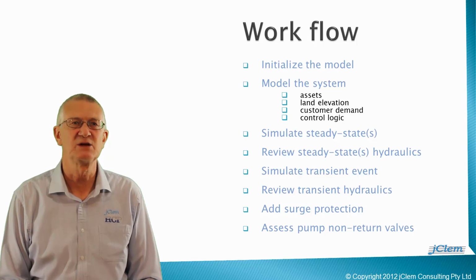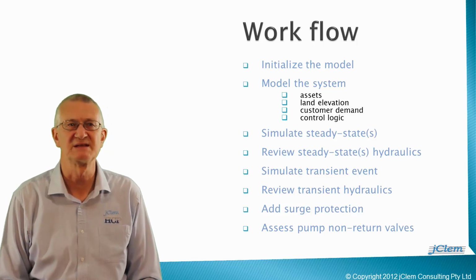In the case study, you will simulate and review the results of a range of transient events. In cases where the transient results don't match the system's design objectives, that is when the case study will move on to adding surge protection. The case study winds up with looking at assessing the non-return valves in a pump station, examining how the fluid dynamics in the system affect how fast the non-return valves need to close.